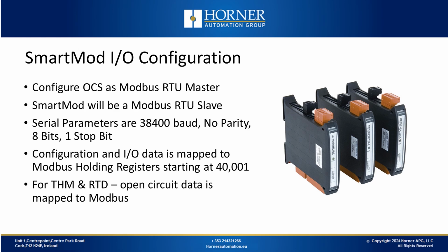Any configuration that needs to be done, as well as reading data at runtime, is done through Modbus registers. This configuration data and the I/O data is mapped to Modbus holding registers. In the case of the thermocouple and RTD, there is some diagnostic data available in Modbus coils, specifically open circuit data in case one of the thermocouple or RTD fails open.